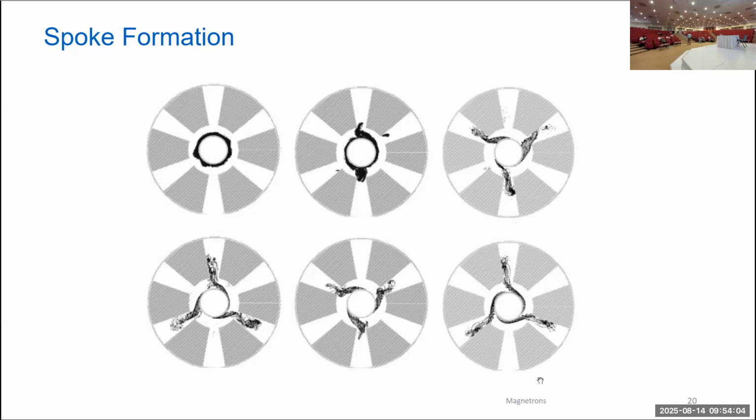Yes, sure. But when you are designing your magnetron, you have to design in such a way that you consider the amount of charge in the spoke and the effect of that spoke on the capacitance of the cavity or even the inductance of the cavity, and then you optimize your magnetron.